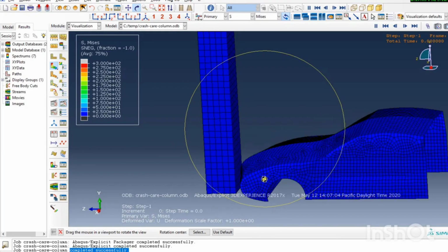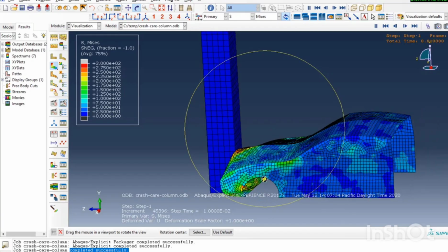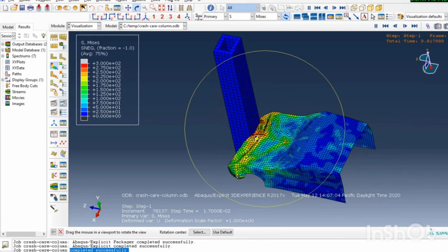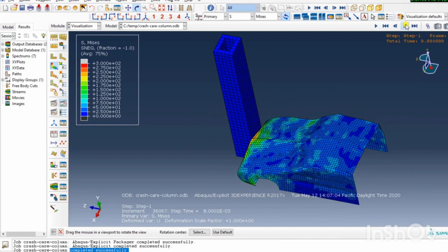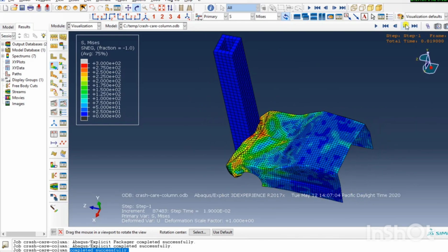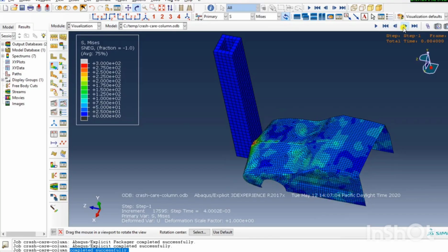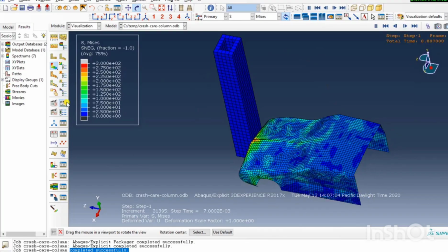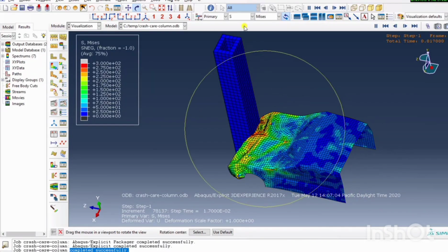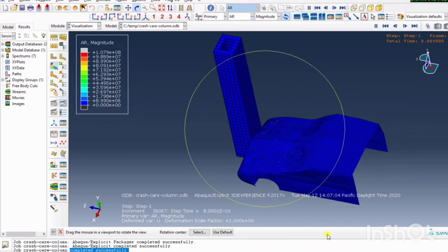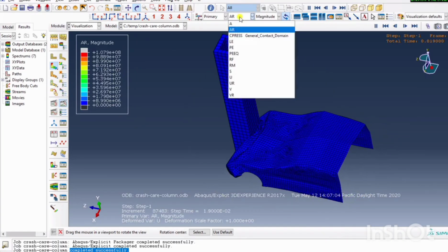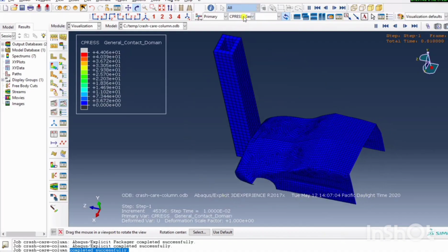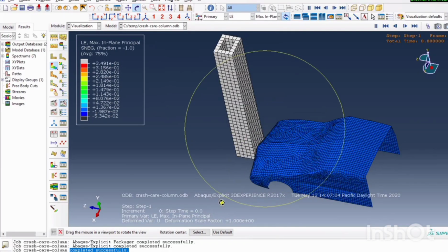As a result of this simulation, it provides detailed insight into the crash behavior. The deformation plot shows a progressive collapse of the front structure, including how energy is absorbed through controlled plastic deformation. Energy plots are particularly important in validating the simulation. Initially, the system possesses kinetic energy due to the assigned velocity. As the crash progresses, this kinetic energy is converted into internal energy, primarily through plastic work. This shows that a significant portion of the initial kinetic energy is dissipated within milliseconds of impact.